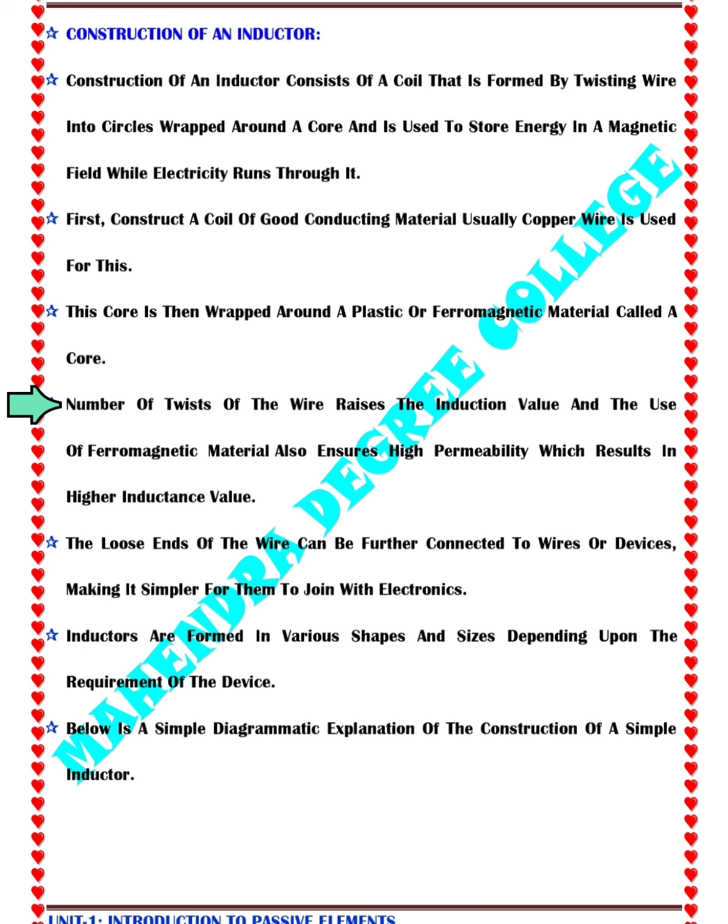The final explanation: more wire turns means stronger magnetic field, that is, higher inductance. Ferromagnetic core means better magnetic field concentration, that is, even higher inductance. These factors help the inductor store more energy and resist current changes more effectively.